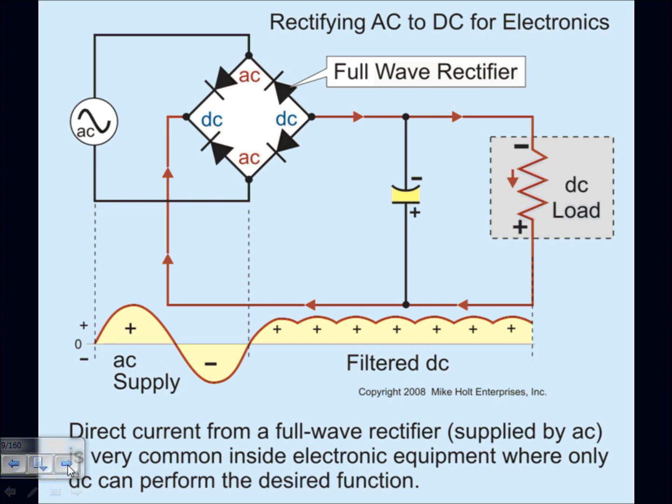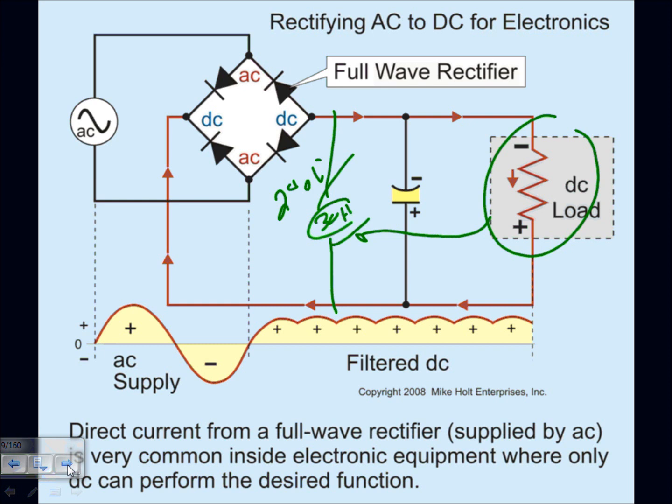So now the main source of DC that we get for DC motors, guys, is AC. So what they do, they have a bridge like this. If I have a DC motor, 30 horsepower, 240 volt DC, the only way I can get DC to power this motor is by taking an AC, because we standardized on an AC system to transmit, distribute, and convert it into DC. You have to rectify it and then dump it across your load, which happens to be the 15 horsepower motor or 30 horsepower motor.